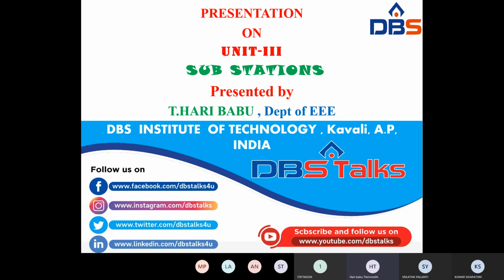So the main equipments of a substation are, first, the power transformer, that is the 33 by 11 kV transformer, then circuit breakers, protective relays, bus bars, lightning arresters, instrument transformers, insulators, isolators, control room, indicating and metering equipment, current limiting reactors, shunt reactors, series reactors, shunt capacitors, coupling capacitor, station batteries, and grounding system. So these are the other auxiliary equipments or operators.